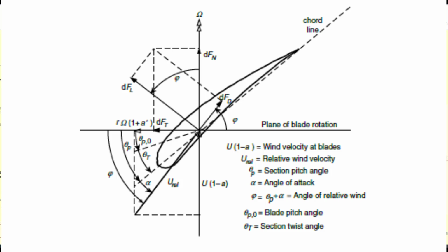You see, after designing a wind turbine blade, it's usually necessary to ensure constructability. For example, if you design a blade where the variation of the twist is too wide, it's often difficult to construct it in the workshop. So the process is now to consider the ratio of lift to drag, which actually tells you how far a wind turbine blade can be lifted by the air.